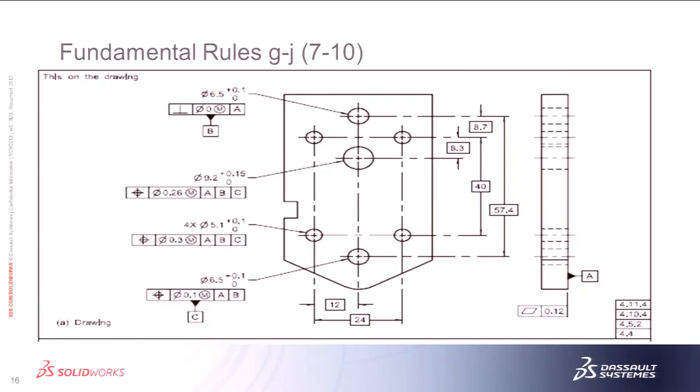It's going to help you limit the amount of hidden lines that you're going to be dimensioning to or show in your front view. And most of the time it's going to be your true profile view too. You can see in the standard that's exactly what they did, their front and their right side view. For optimum readability, they also grouped all the GD&T on the left side and then the basic dimensions on the right in between the views. Very important too, you should always try to dimension between the views. So if I had a top view too, I would most likely pull the 12 and the 24 to the top, so it's in between the top and the front view. That's not a shall, but that is a very good fundamental rule to know and try to go by.